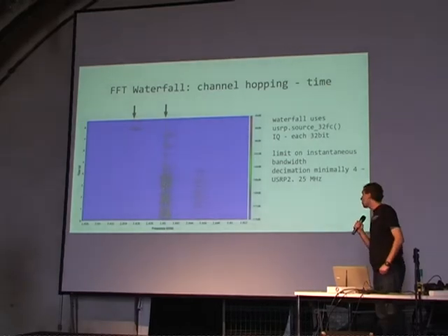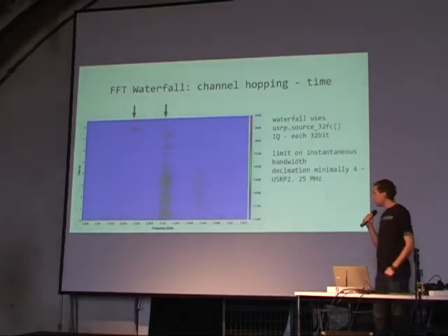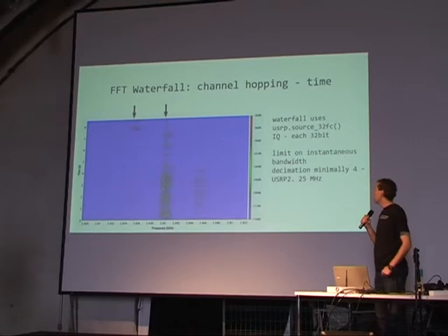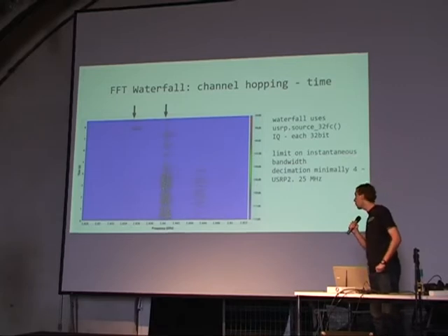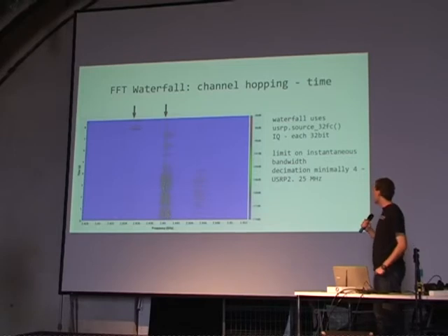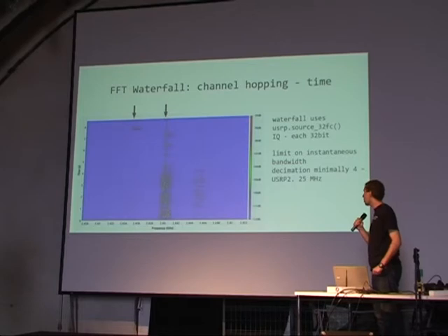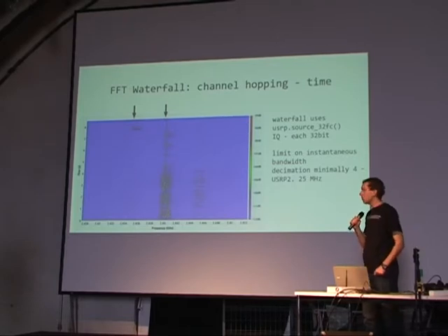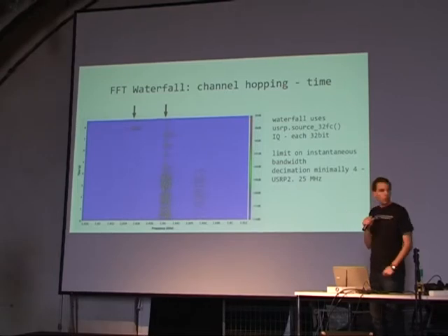What we see here is an FFT again, but it shows that a device, which is the first leftmost arrow, is operating on a channel that is corresponding to 2.434 gigahertz. Sorry. And then there's interference that occurs, and the device changes the channel and stays operating within that channel and doesn't continue to work there. So the device reacts to the interference, does appropriate channel change.